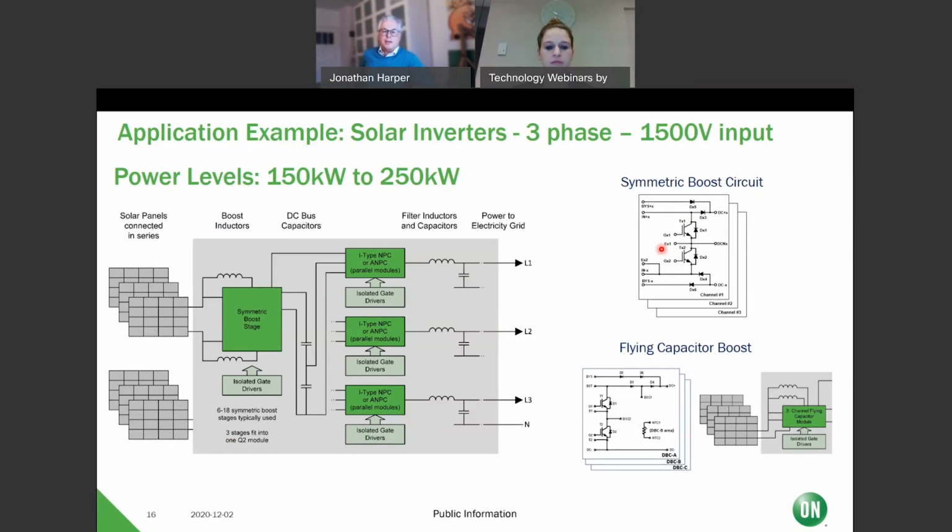Normally at discrete level, that's what we do at the moment, because getting the inductances right is a bit tricky. You can get them exactly right, but then the models are too complex. So that's an area we're looking at. But for simulation, worst case, we use discrete components, and we certainly offer step files to the customers we're working with.